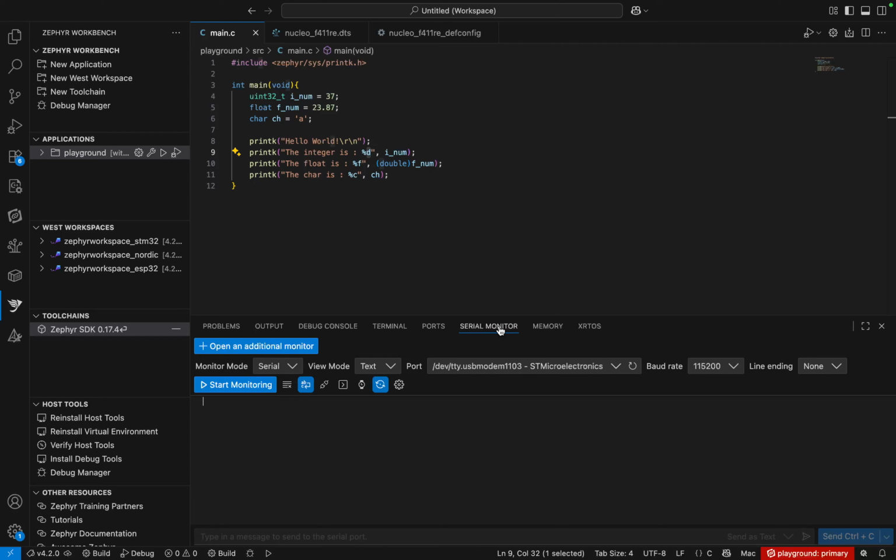And just as you might already know, if you don't know, that's okay. The next few videos after the login is going to be about serial communication, so then you will understand what is going on. But there is basically information being exchanged between the microcontroller and the host computer, and they have to agree on what is known as a baud rate. That is the rate at which information is sent, right? So how many bits is pushed per second. They have to agree on that.